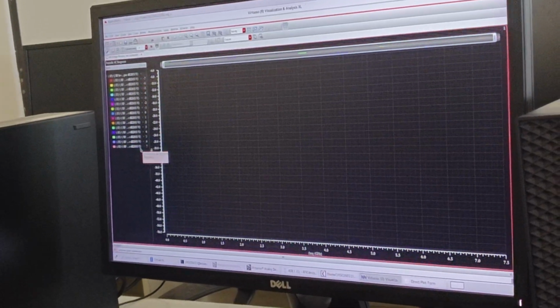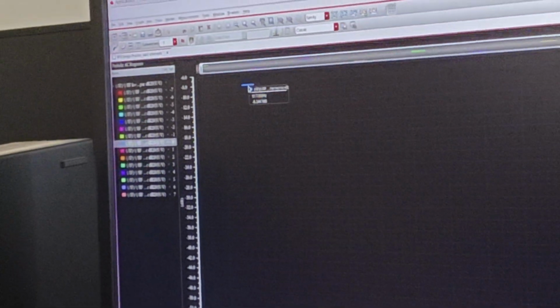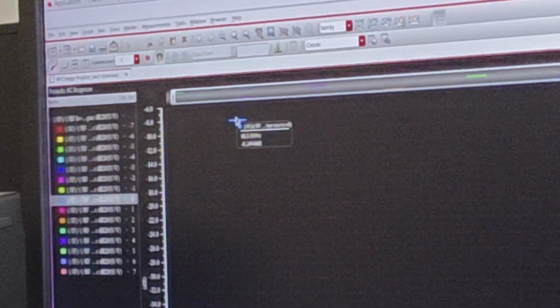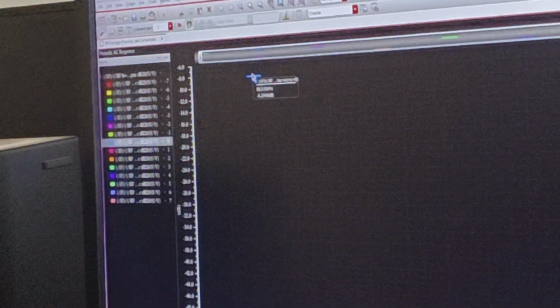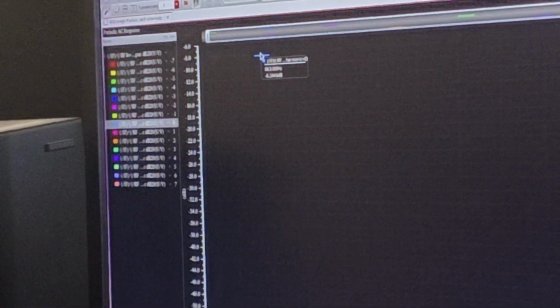So let's say the 0th one, it came around here, right? 800 megahertz to 1 gigahertz. This is my conversion gain. What is the conversion gain? Minus 8.24 dB. Means this is a lossy circuit. This conversion gain is minus 8 dB.